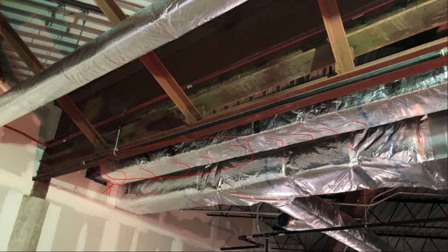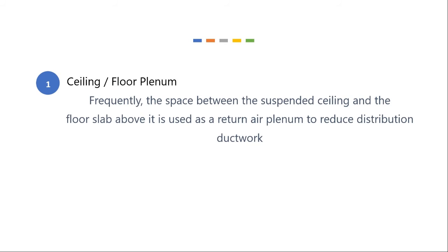We want the heat to end up in the room. And of course, the cost of this insulation up front must be considered versus the cost of losing all this heat energy over the lifetime of the system. And obviously, the cost of the insulation is much, much lower.